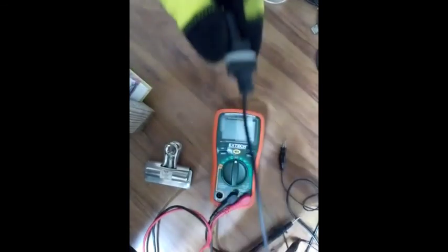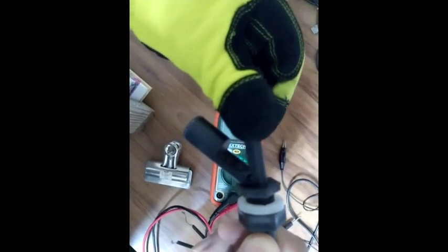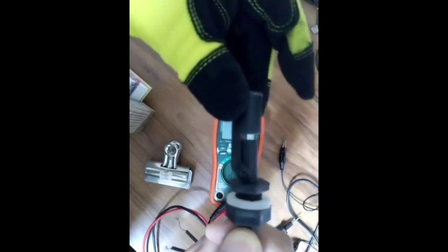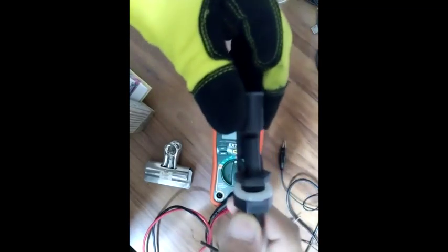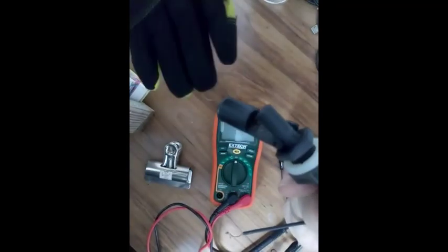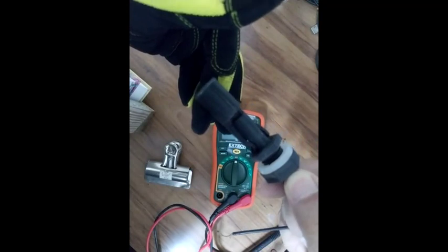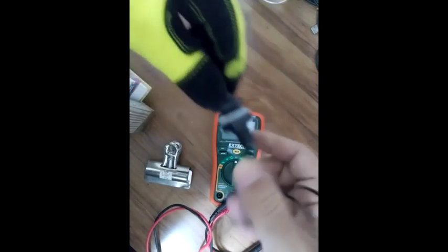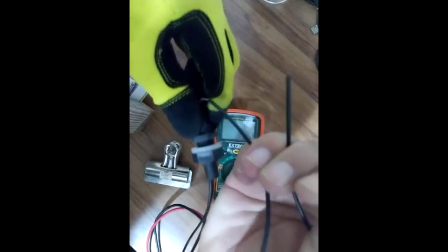All right, I have a level sensor in my hand right now. Inside this part here, there's a kind of reed switch, or sort of contact, two metals, and when those two metals are aligned with a magnet which is in the float of the level sensor, and notice there's a hinge right here, and that hinge only has one position. If you install it this way in a vessel, when the water level rises, it will align the contact with the magnet, and therefore you have a short circuit between the two terminals right here.